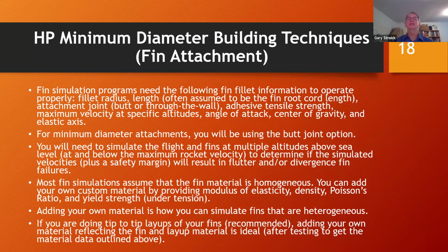So you need to know the adhesive strength, because that's going to be required in the modeling of the fin attachment when we look at whether it's going to fail or not during the flight. You're going to want to make sure, as I mentioned earlier, the velocities at specific altitudes, so we can model a couple of different points and make sure that we're looking at the right area of the flight in order to make sure what the maximum forces are on that particular fin.